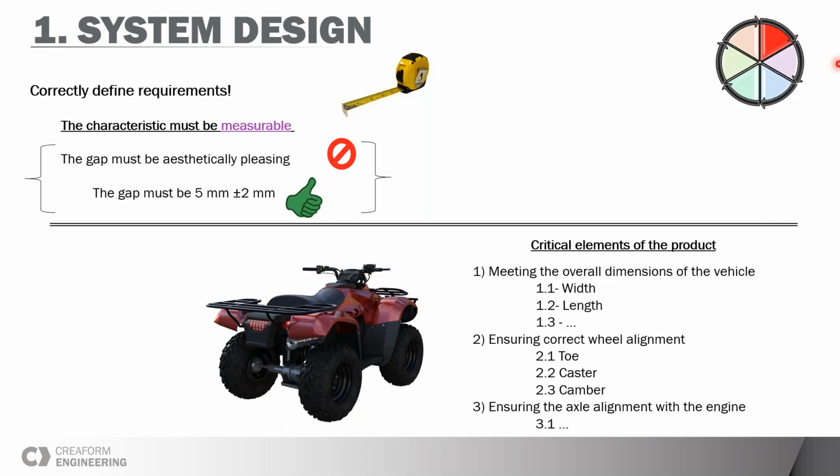So there are multiple ways. If you are used to some kind of product, if you have prior knowledge, you may already know what tolerance is acceptable for that kind of product. So it depends on your prior knowledge. If you don't know, a good way for an easy product is to just prototype the product at the edges of the tolerances, and you will be able to assess whether or not it will work.